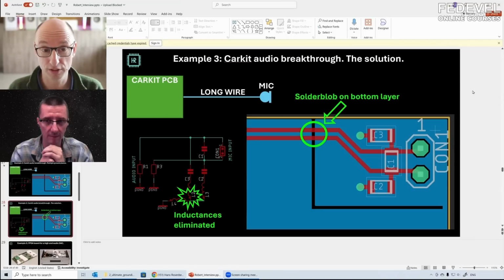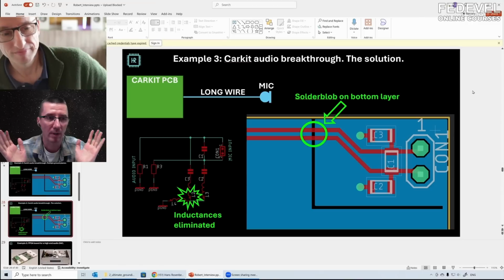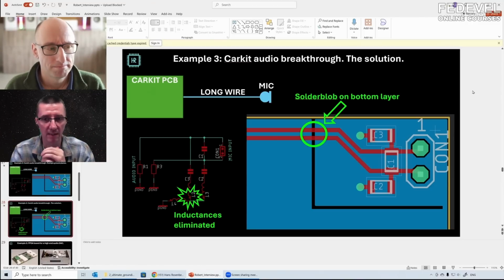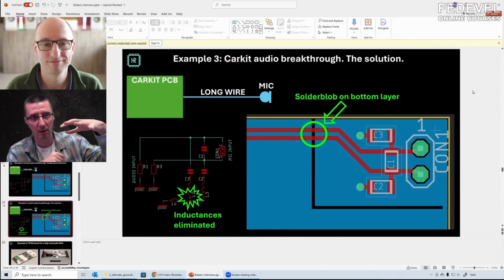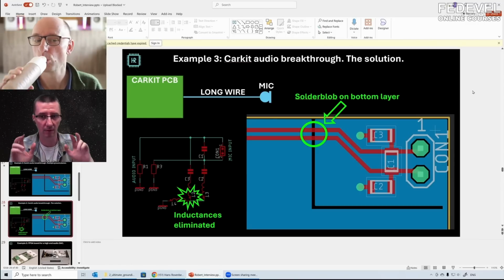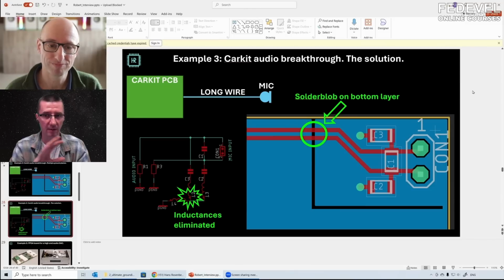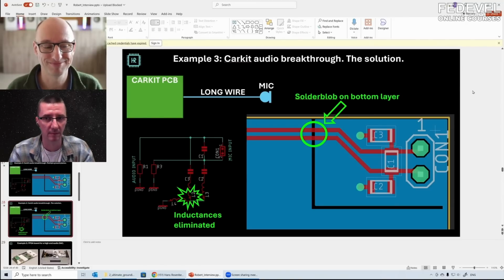Yeah, there's only one reason why you should separate ground. That's when you have an actual galvanic separation, like an AC DC supply or something. But other than that, maybe there are some examples. I don't know, maybe when you are designing very sensitive devices, but for digital boards, what I normally design, I never had problems with a solid ground plane. Even, I need to say, I had digital parts on the top of the board and analog parts on the bottom. It was a 12-layer PCB, of course, so each had its own ground under the signal, so they didn't mix together. It was working perfectly fine. Yeah, I can imagine.